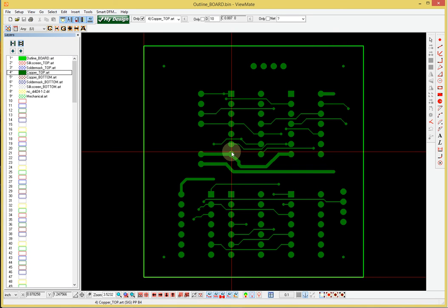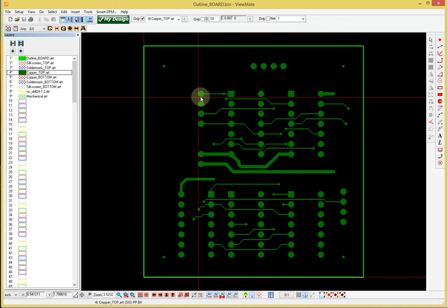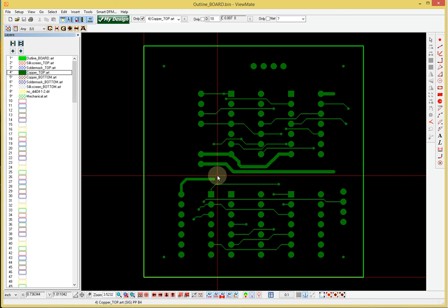It doesn't matter what it is connected to. The file doesn't care. It doesn't know what's a chip or a part or a component. It's just copper features on the layer. Notice that there are no holes, right? Because this layer only shows the copper features, and the drilling of the holes, if that is necessary, comes at a later stage.